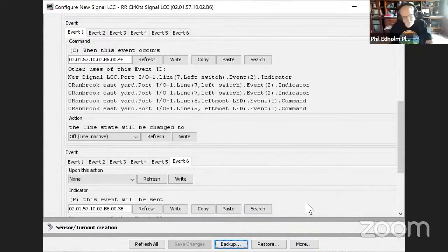Can I make another suggestion of an area that this actually would be absolutely interesting? Any modular group that's doing any sort of mainline railroading where they want to have some sort of overlaying control system, because you literally could have plugs on each of the modules and plug them together. You could have an LCC node on each module, and the chain of those would give you something that, if you were really fast, you could potentially use to build a signaling scheme on the fly for a specific layout configuration. The modularity really makes sense, because the nodal intelligence stays with the module. And really, what I'm talking about here is how centralized you want to do things versus how distributed.